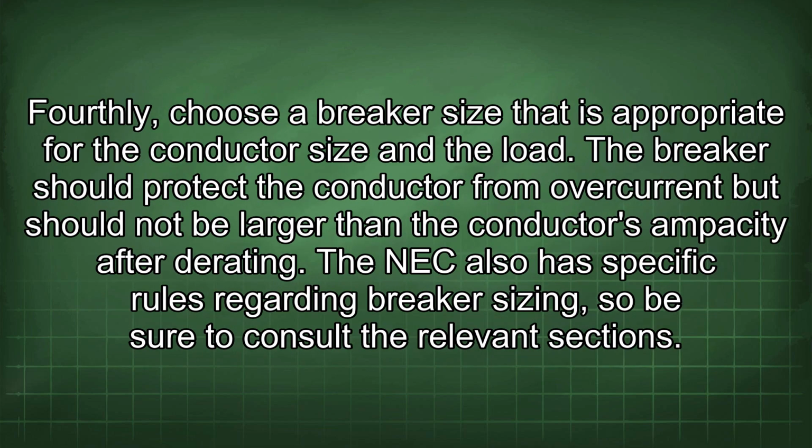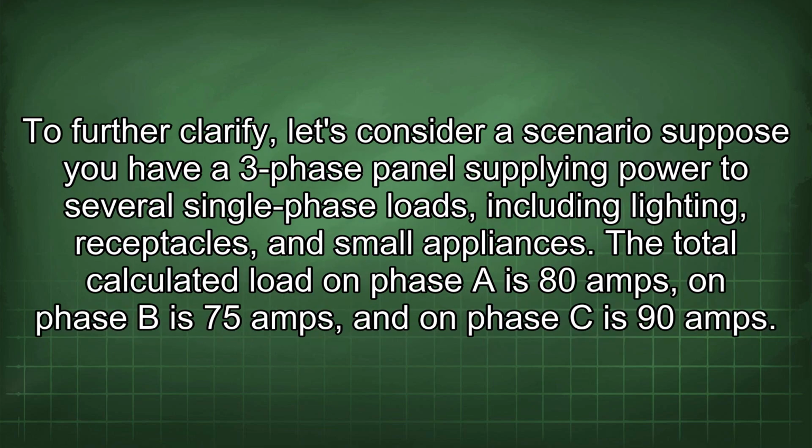Fourthly, choose a breaker size that is appropriate for the conductor size and the load. The breaker should protect the conductor from overcurrent but should not be larger than the conductor's ampacity after derating. The NEC also has specific rules regarding breaker sizing, so be sure to consult the relevant sections. To further clarify, let's consider a scenario. Suppose you have a